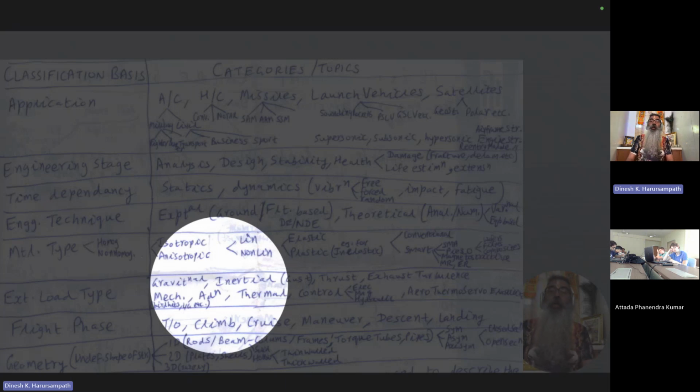This is especially important in terms of the distribution when you go to much longer or larger structures, for example space booms. In satellites, even though while launching and at the point of detachment from the launch vehicle, the payload, which is a satellite, might look very small, after it gets into its orbit, typically certain antennas are deployed, and some of these antennas are fairly longish structures. Since they are quite far from the Earth as well, you will see that there can be a gradient involved as far as the small g, that is the gravitational constant, is concerned.